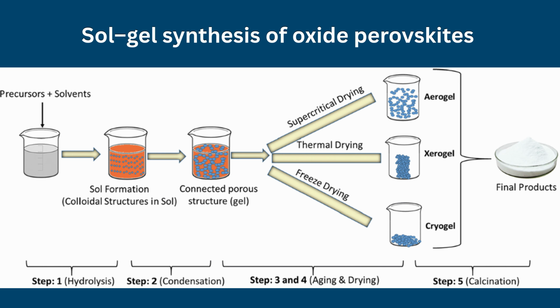Emerging techniques. Additional fabrication approaches include sol-gel processing, electrodeposition, and laser-assisted patterning. The sol-gel method allows precise control over film morphology and defect density, while electrodeposition enables uniform coating on complex geometries. Laser ablation has been successfully employed for module patterning and interconnection, improving cell-to-module efficiency.